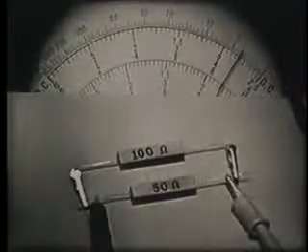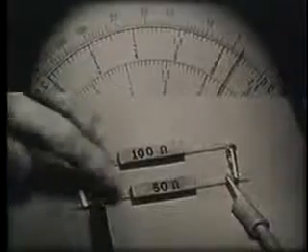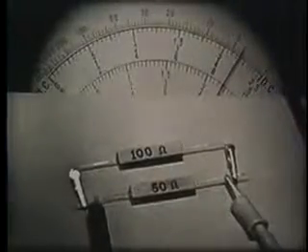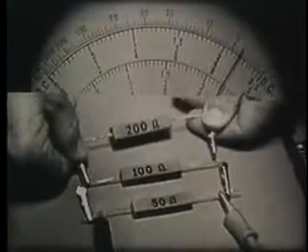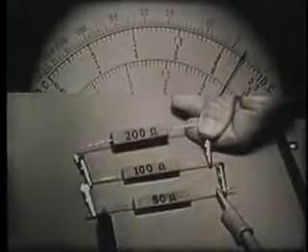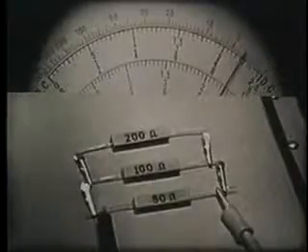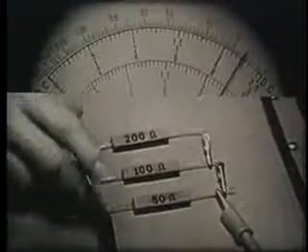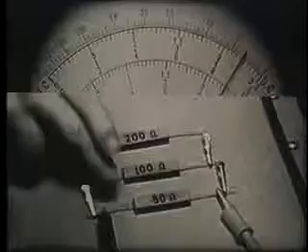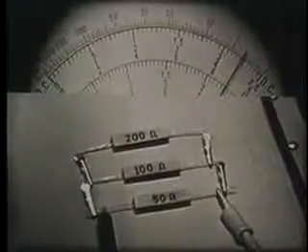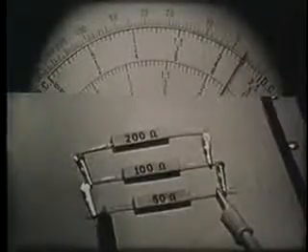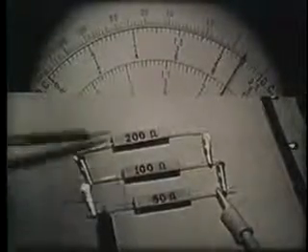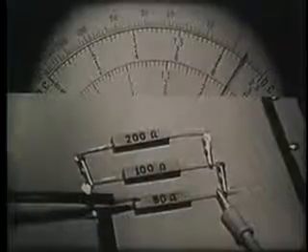Resistance has decreased, but why? Remember, we've increased the cross-sectional area of the total resistance. Now, let's add a 200 ohm resistor in parallel with these two. Watch the reading. It decreases more. Remember, each time we add resistance in parallel, the cross-sectional area of the total resistance increases and actual resistance decreases. In fact, total resistance in a parallel circuit is always less than the smallest branch resistance. In this case, the smallest is 50. And check the reading. It's less than 50.